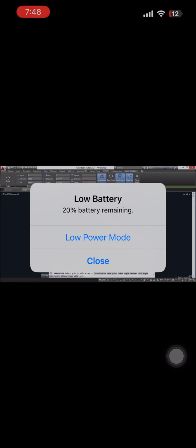The default polar array appears. You can set its parameters up here. Let's say I want 8 chairs. I'll type 8 tab. I'll close the array. And it is associative, so I can click on it in the future and I can make changes to it if I want. Let's close that. Now over here, let's make a path array.